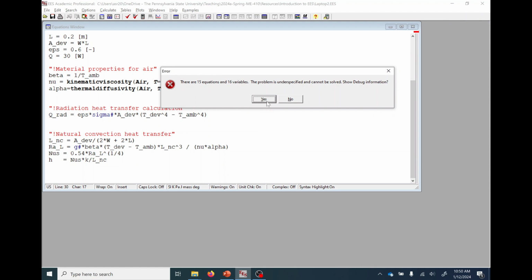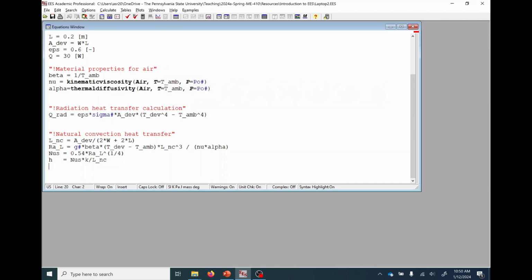So there's an extra piece of information here that I forgot to calculate, or an extra variable that I forgot to define, or probably had a typo somewhere. So let's do the following to try to debug that. I'm going to comment out, and I can do a block comment in braces like this, to hide some of the unknown quantities, or some of the equations that are probably part of the problem, and work my way up until I've tracked down anything I missed.